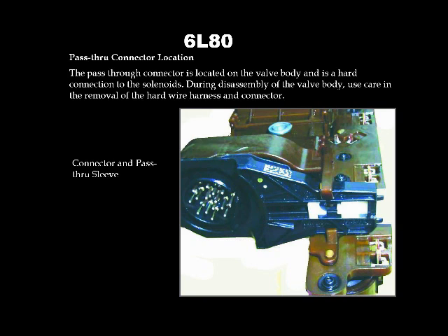Pass-through connector, you've got to be kind of careful when you unplug the pass-through connector. When you unplug it, it's going to be a snap lock. This is the snap lock right here. You physically have to snap that out before you can pull the harness away from the TECM. If you don't unsnap it, you're going to end up breaking the harness trying to separate it from the TECM.